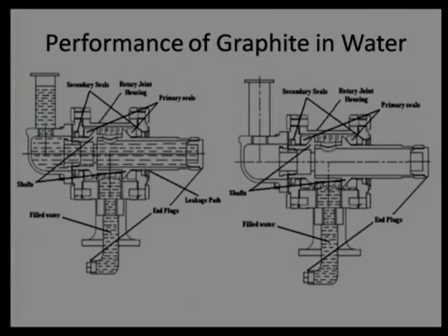In this situation, the availability of moisture at the carbon graphite and stainless steel interface is reasonably low, and we find the coefficient of friction is very low, in this case equal to 0.15. If we do not use moisture at all and run this unit at 100 degrees centigrade, we find a high coefficient of friction, almost 0.25.